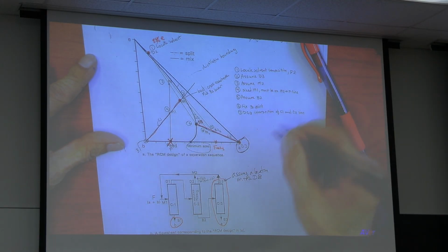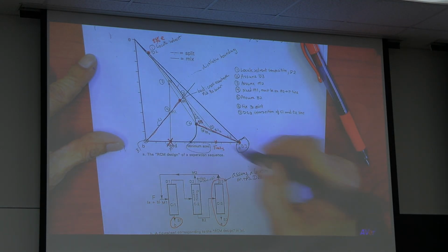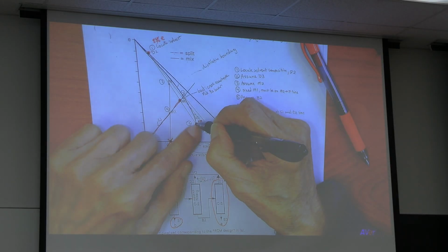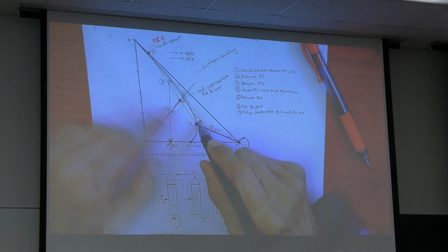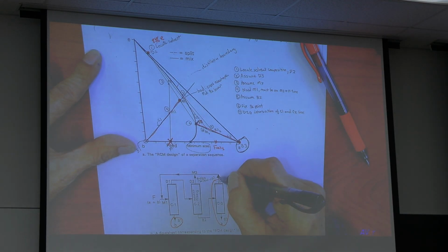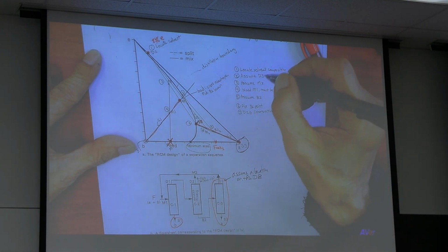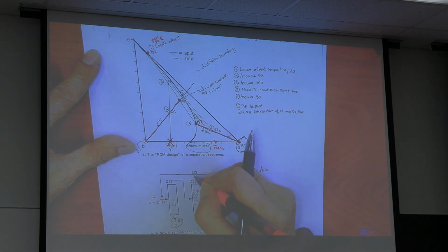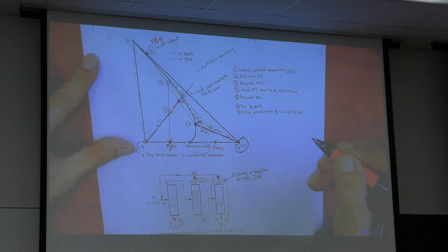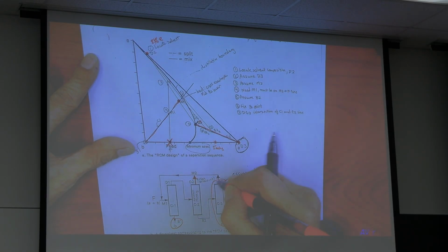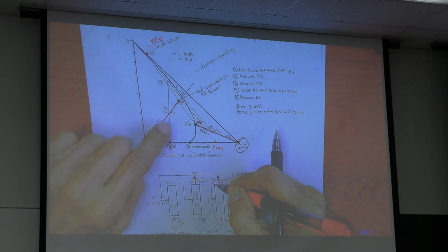We assume this is on the distillation boundary so that D3, later on, you mix with the solvent recovery, you can create a new feed in this region.